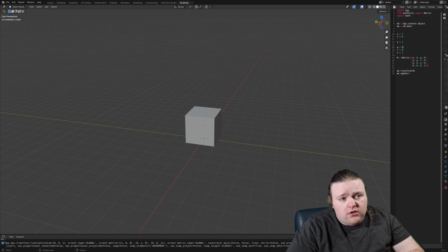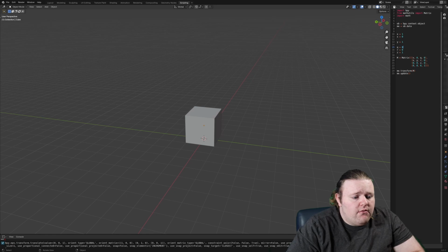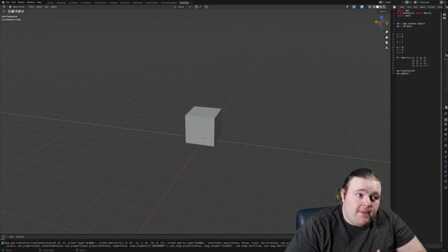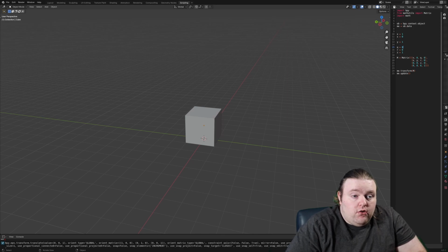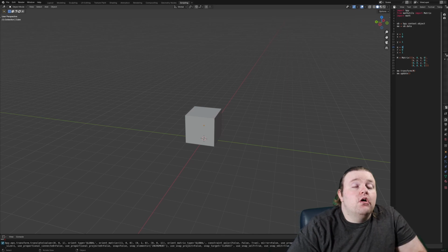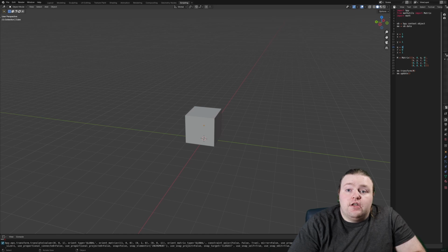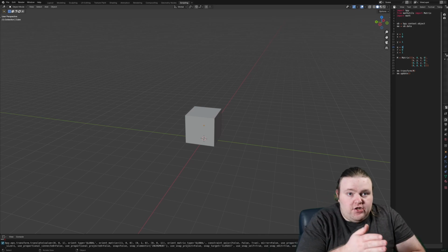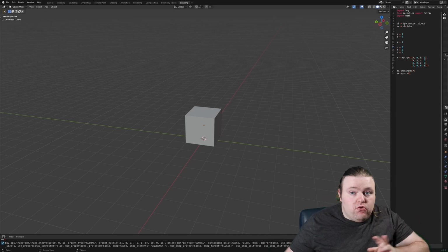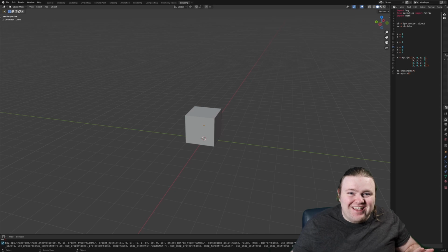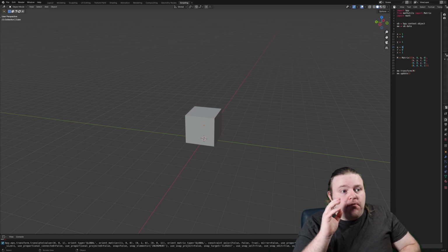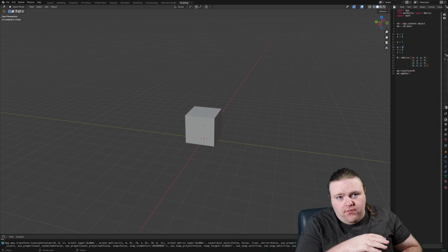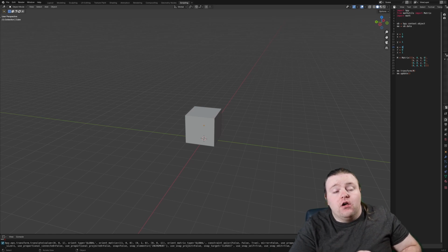The other thing is that he mentions that if you don't have a more open platform printer, you probably are SOL on your ability to find a way of dealing with it, if the slicer available to you doesn't have skew compensation as a feature, which we're going to get into why I think that is inexcusable. Every single slicer should have this as a feature. It is actually so easy to do, which is what we're going to get to here in Blender.